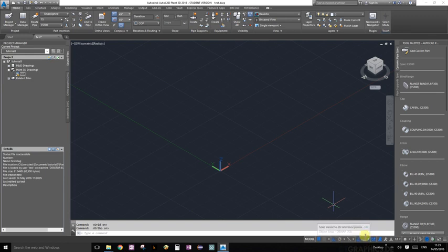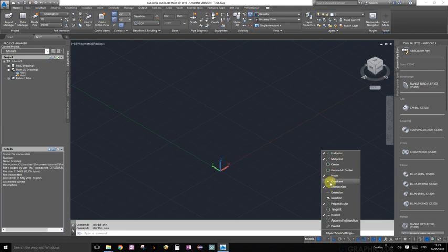And one major important thing in AutoCAD is always going to be the snap on, which means when you have a line or object, which point can you select? It's actually very important. So go ahead and click on the little down arrow on the snap, and here it would give you an overview of which options you have selected. I'm going to show you.